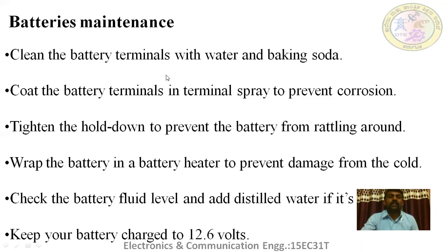Because of some conducting materials, either cadmium is used or zinc is used at the terminal, and in some lead acid batteries there is some corrosion. So that corrosion can be cleaned by using clean water and soda, or there are some solutions available to clean the terminals of batteries.